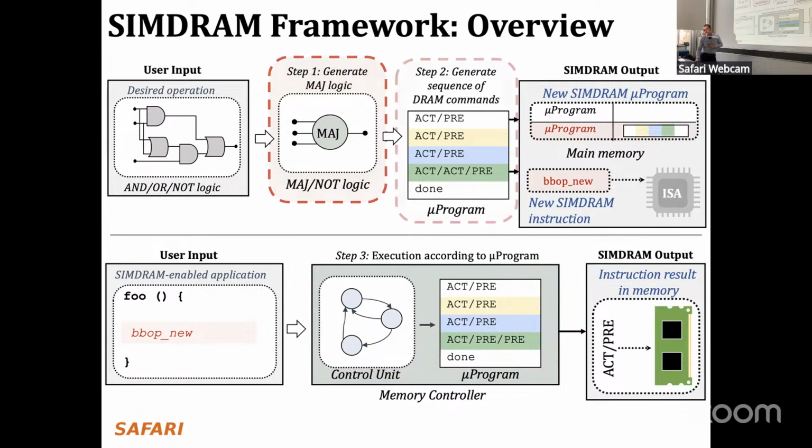And then we have a pass that turns that majority-inverter graph into commands in DRAM, basically RowClone commands, triple-row activation commands, consecutive row activation commands, etc., so that you can satisfy what the circuit is doing. Okay? Majority and NOT, basically.